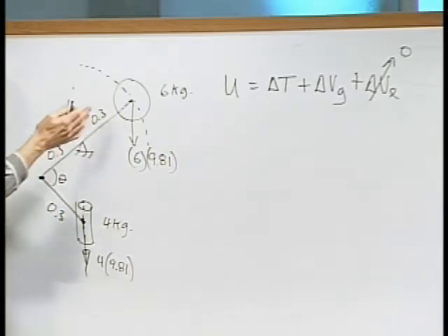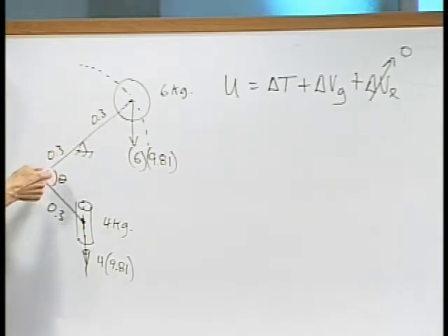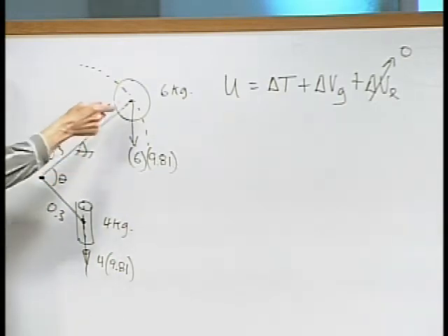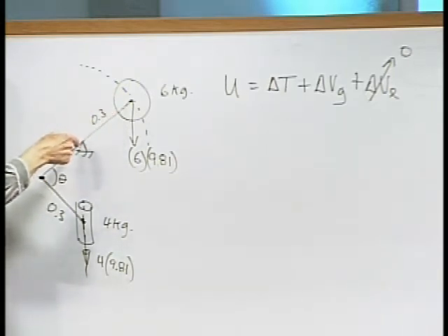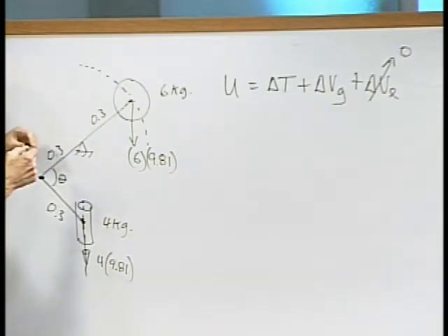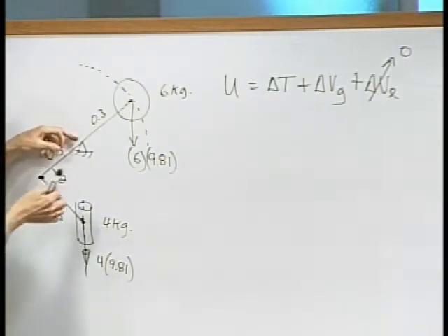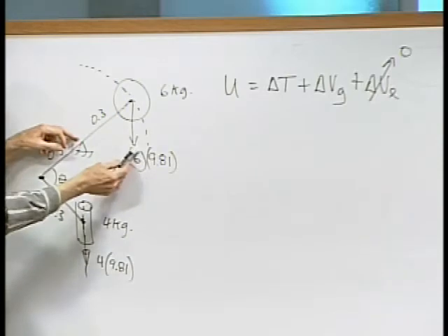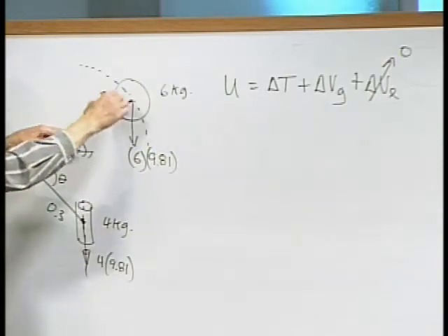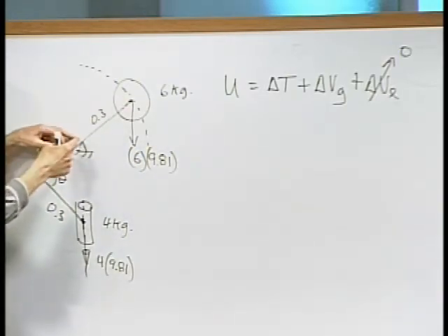In a static configuration, this is at 60 degrees when we let it go. In a static configuration, before we let it go, this bar is carrying what? The weight of the ball. Is it carrying compression or tension? Compression. And there's some bending in there too, isn't it? Okay. There's some bending because of the lever arm here, and there's a component of this weight that actually creates a moment about this pin.